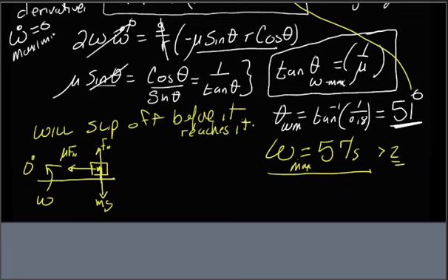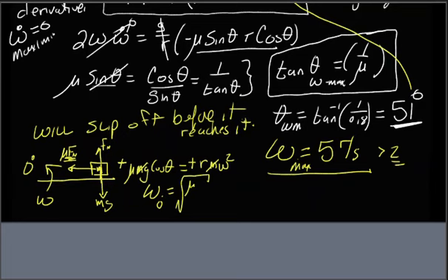And from here, we get mu mg cos of theta, that's mu Fn, is equal to, and it's negative r m omega squared, our acceleration term. The m's go, the negatives go, and we find omega at 0 degrees is the square root of mu g on r, which for, again, our numbers will work out to be 3.9 radians per second.